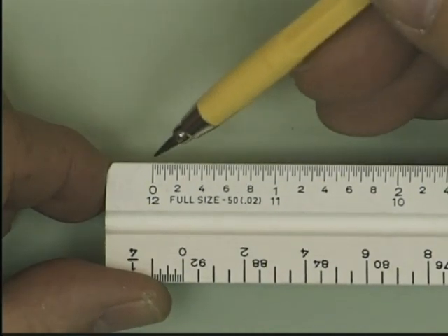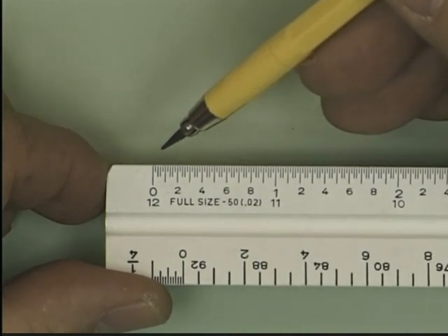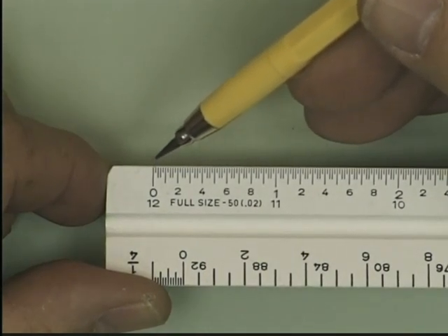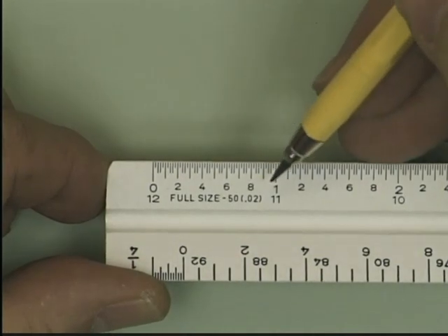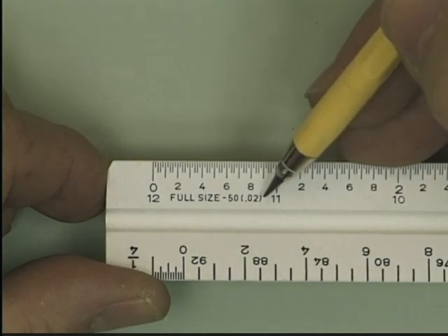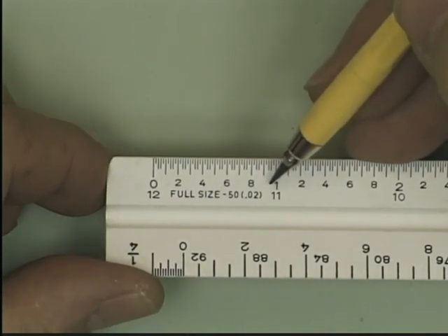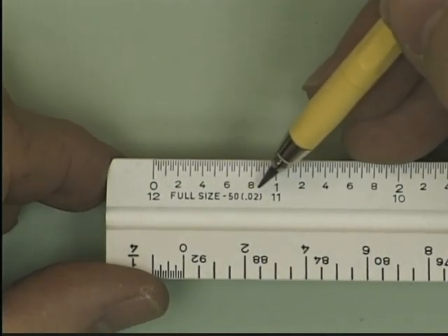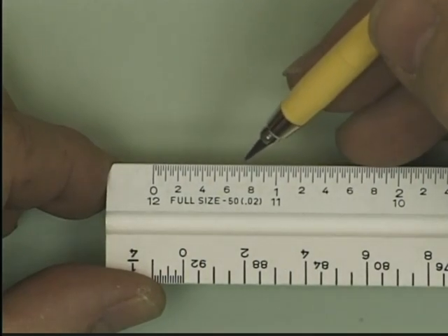Each one of these smallest divisions is 1/50th of an inch. You do a little arithmetic. Let's see, 1 inch divided 50 times. That means the smallest division on here is 0.02 inches long. 0.02 is the same as what a machinist would call 20 thousandths of an inch. As a matter of fact, math teachers and machinists don't talk fractions, or decimal fractions, the same way. Whereas a math teacher might say 2/10 of an inch, a machinist would never say that.